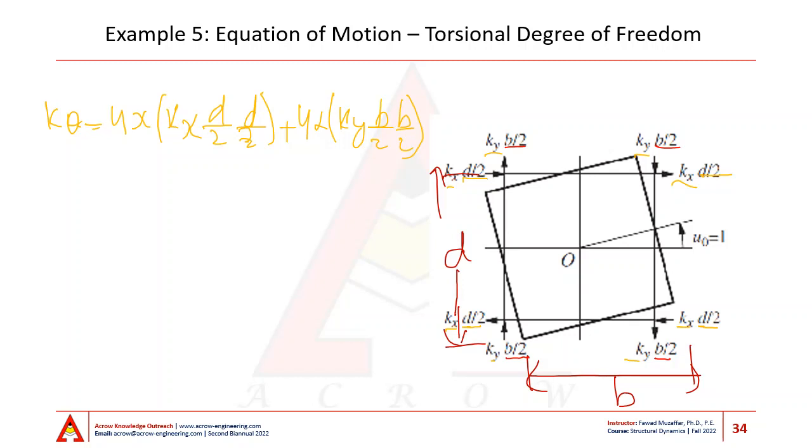Note the product of the first two quantities is the force, and force multiplied by the third quantity inside the round brackets is the moment. Four is used to scale up or multiply the response of a single column and consider the effect of all of the four columns because all of the four columns are identical to each other.